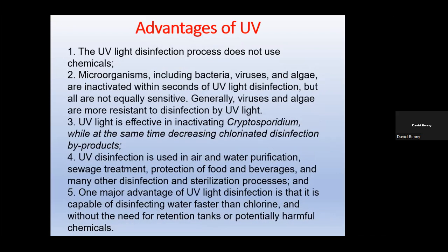Some of the advantages: it doesn't use any chemicals. The microorganisms, generally the lower class of organisms, are made inactive by the UV radiation. It is effective in inactivating cryptosporidium, which can be problematic.